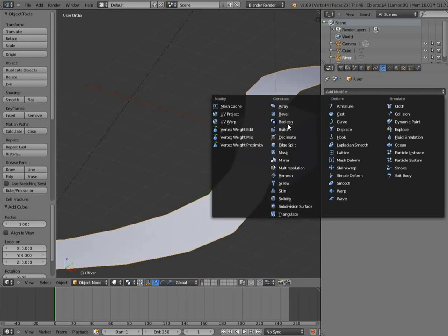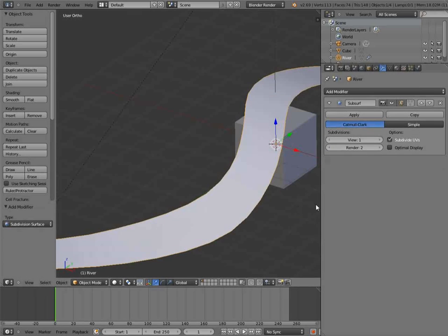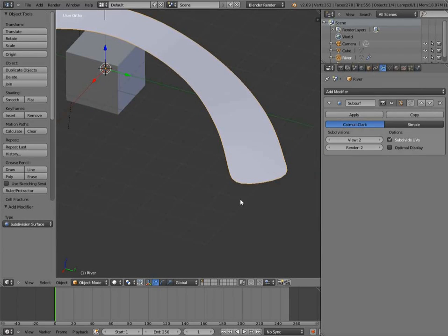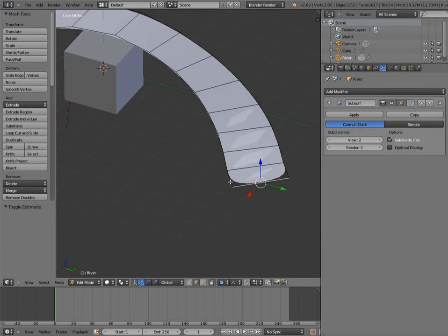Obviously you want to improve this shape's quality, if you will. So you can just add some subdivision to it, about twice will do. But you see these rounded edges, we want to sharpen those up. So select these 3 and press Shift E and stretch it out.